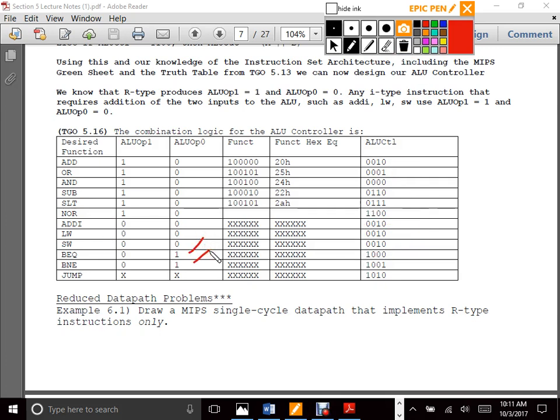Branch equal and branch not equal have the same ALU opcode. What's going on there is the output that's being sent in is 1000 and 1001. And then for jump, we don't care what it is because it's just sending a value out. This could also be don't cares, because we don't care what's being added. When we have jump, the jump value only adds a 1 if that AND gate within the controller fires, everything else is 0, right? As a result, register write is 0 and mem write is 0, so there's nothing that's going to be updated. Right, does anybody have any questions about this?